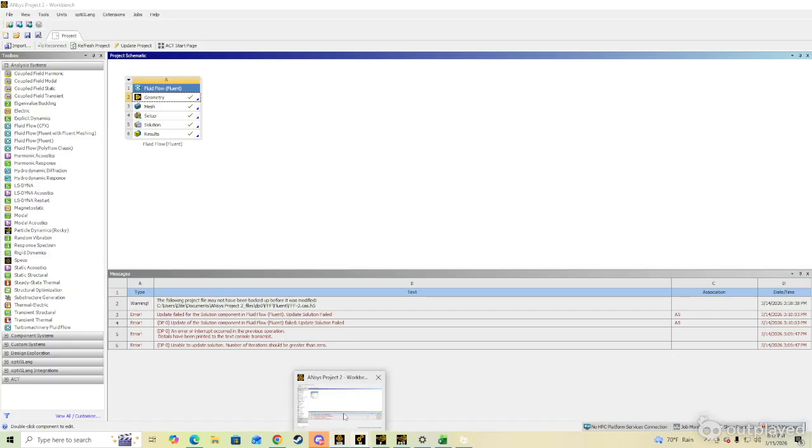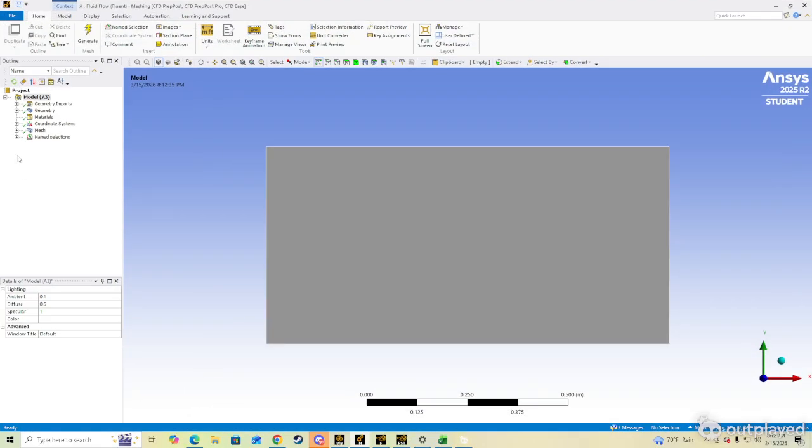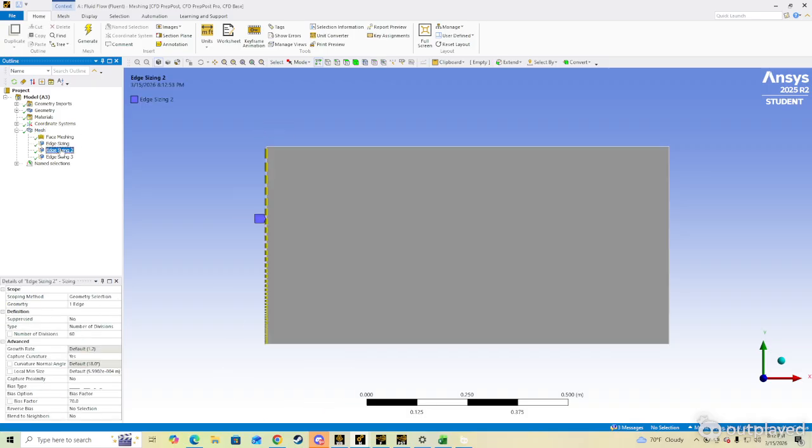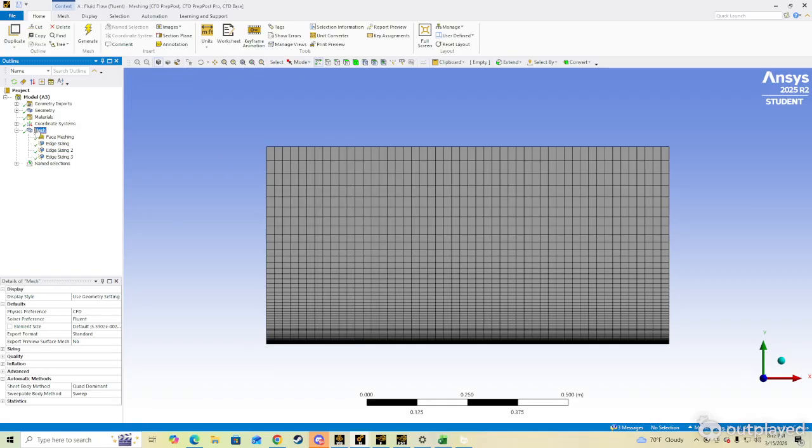Next, mesh. Here's the mesh. First thing was to select the face, then we set up an amount of boxes in total over the whole face, and then to get it to be closer on this side, we set up some edge sizing, and then a reversed edge sizing on that side. That got us the little thin things. Turn smoothing off, that's everything.